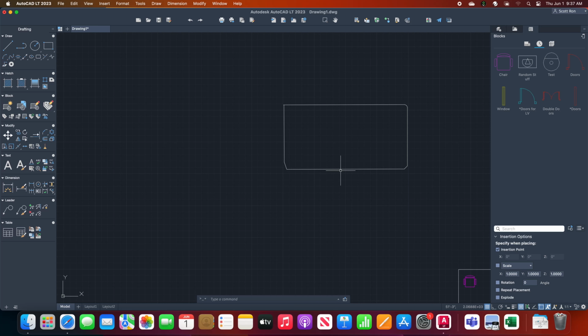Questions? How does it know whether to make it 70 degrees on the top or there? It'll always be from the first line going to the second, the one that you selected first. When I gave it an angle, I had to select the first line, and from there it calculates the angle going to the second. Had I chosen that one first and that second, you could have seen the line break that way. Questions?